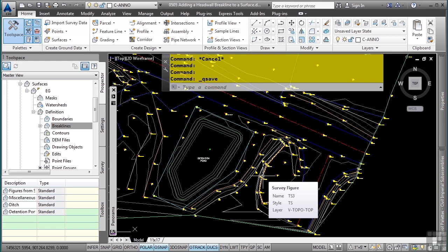Head wall break lines are useful when you only have either the top or bottom northing, easting, and elevation of a feature and either a consistent elevation difference between the points or a measured distance at each vertex. This depth would, in most cases, come from the surveyor's notes.